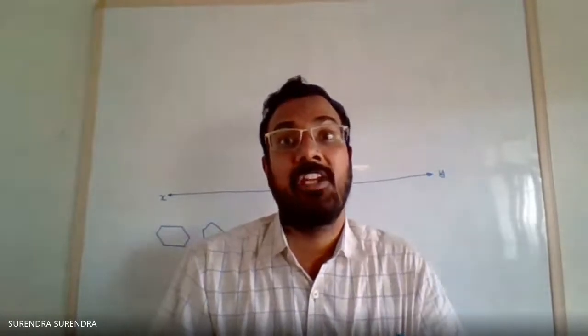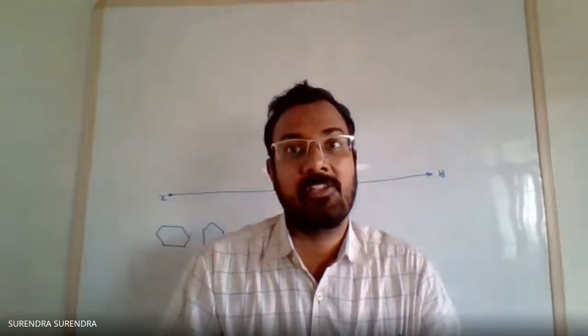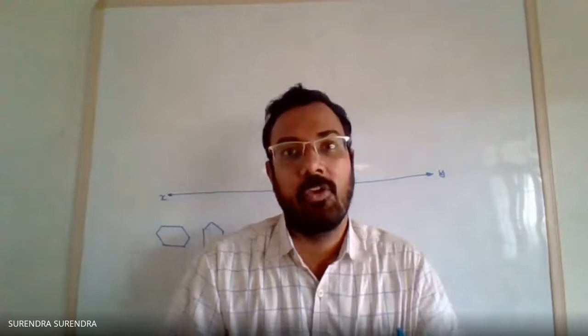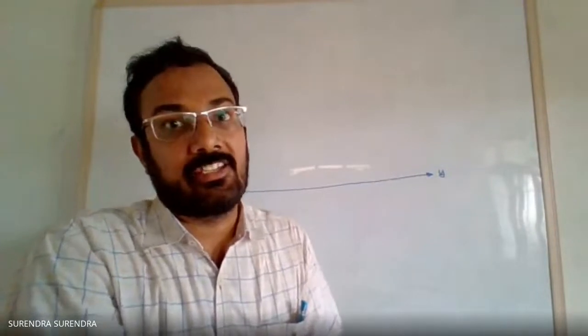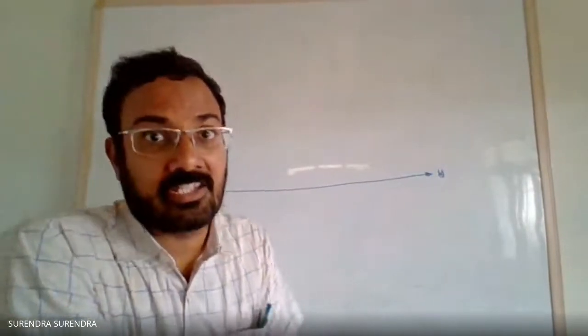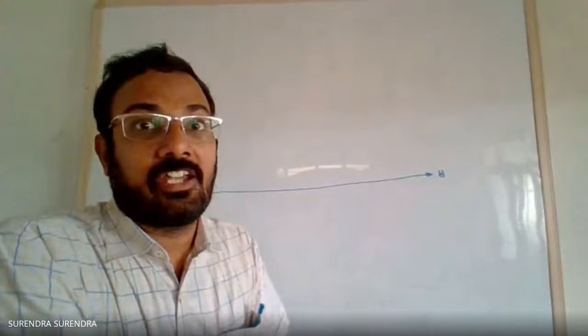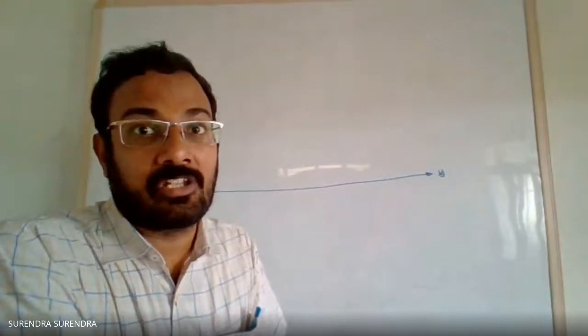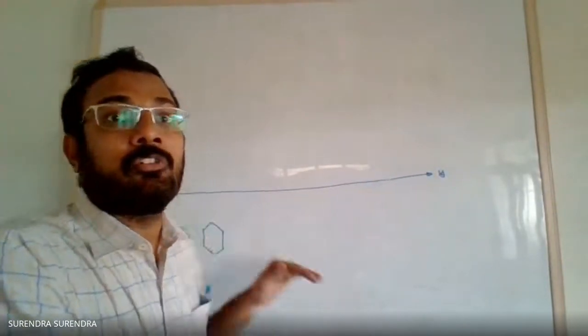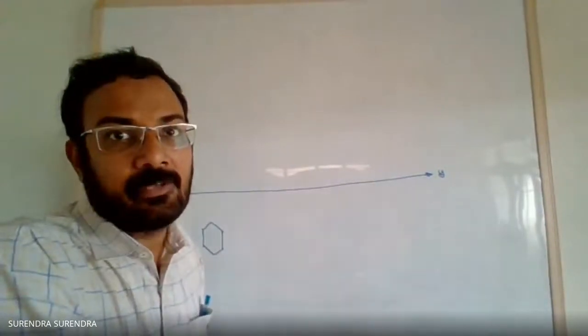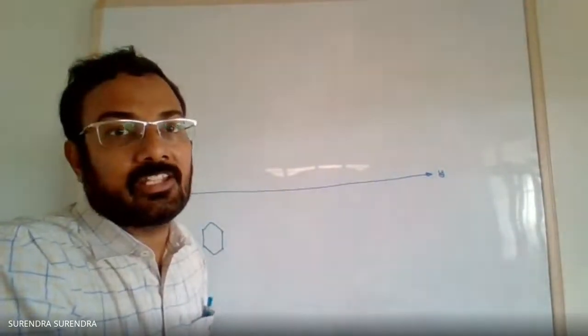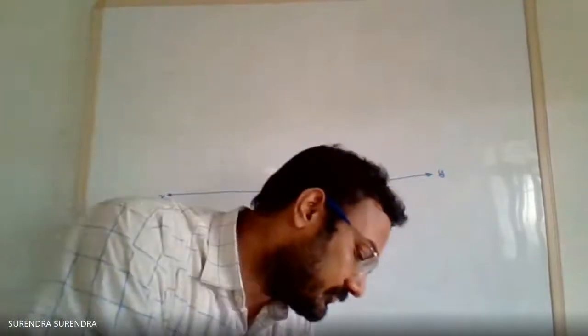Now, as we have to rotate based on the edge, it is an edge-based problem. In the initial view, we have to draw the solid with the edge perpendicular to the xy line. Already we discussed it while discussing planes. Whenever it is an edge-based problem, at least one edge must be perpendicular to the xy line in the initial view.